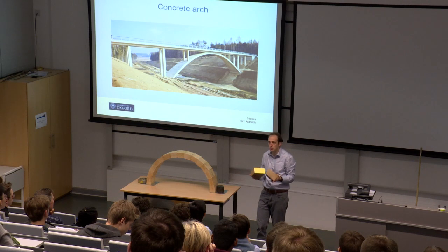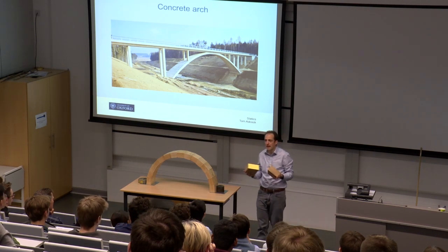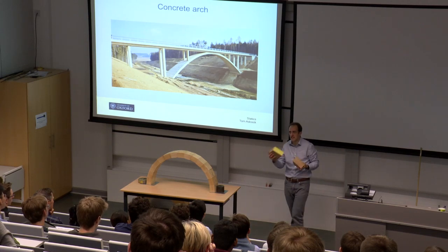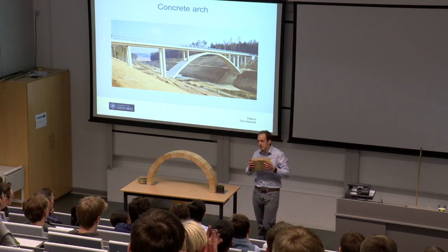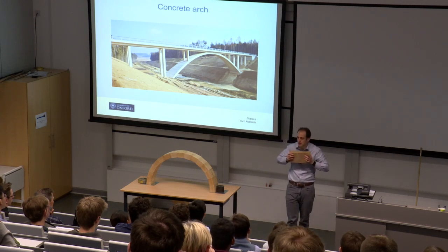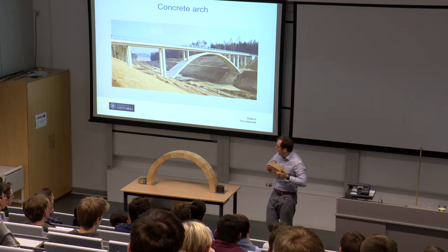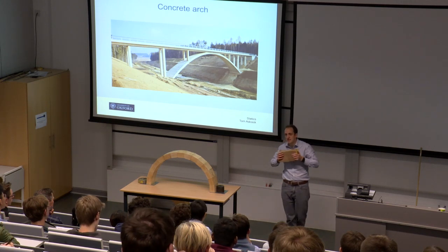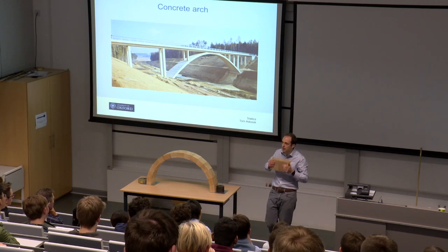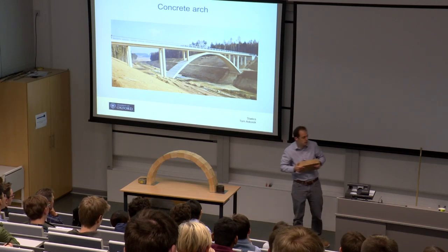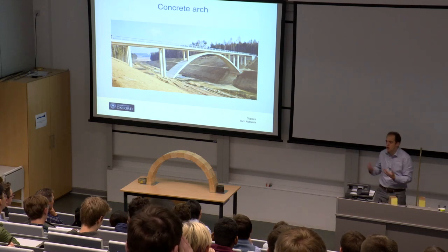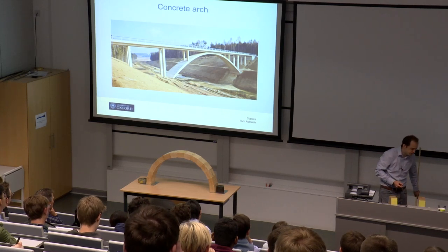Now, that's not going to be true for steel or something like that, where it's equally strong in tension as in compression. But there are many materials like concrete, like bricks and mortar, where things are actually much stronger in compression. And in an arch, the dominant load is actually being carried in compression. So it's a very efficient way of using that material. That's why it's so widespread, particularly for traditional materials.